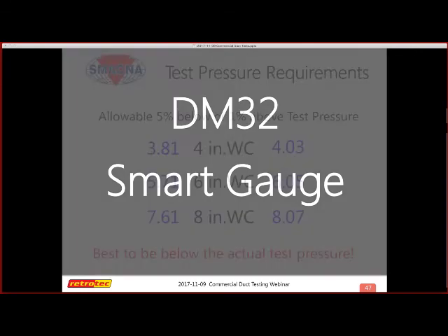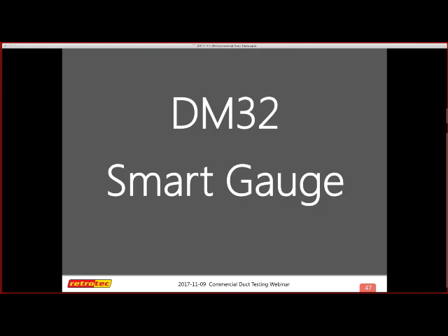So Maggie asked another great question. She says, well, how are you doing the sectioning, or who determines that? A lot of times it's really just guys in the field who understand this is about the amount of duct work we normally test, and they just cap it off. Sometimes they'll put on an artificial sheet metal cap, and all of the trunks are usually just covered with what we describe as duct seal. It's just a sticky plastic that usually goes on all the ends of the trunks.